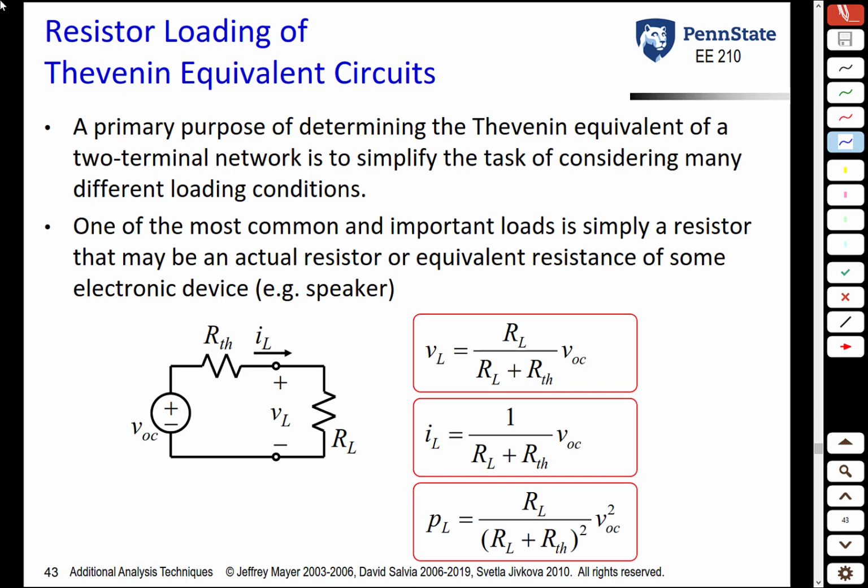In today's video lecture, we're going to finish this packet of notes by considering some applications of Thevenin's theorem. The first one is talking about resistive loading of Thevenin equivalent circuits. As we mentioned earlier, one of the advantages of Thevenin's theorem is that if you have a changing part of the circuit, for example, different loads that you're considering, rather than reanalyzing the whole circuit for each load, what you can do is replace the whole circuit except for the load by its Thevenin equivalent, and then you have a much simpler circuit that you can analyze for each of the loads that you want.